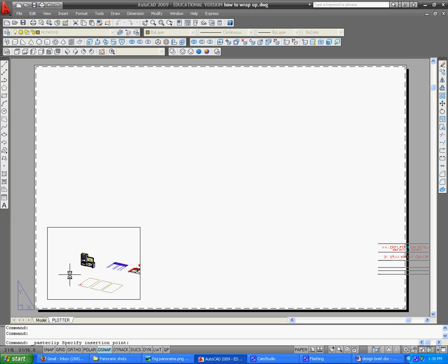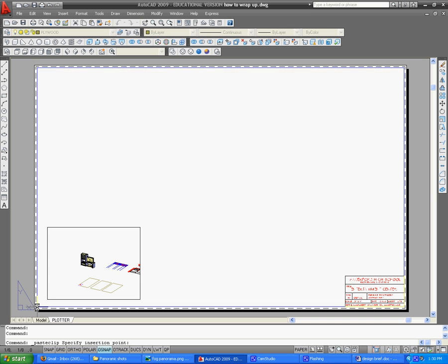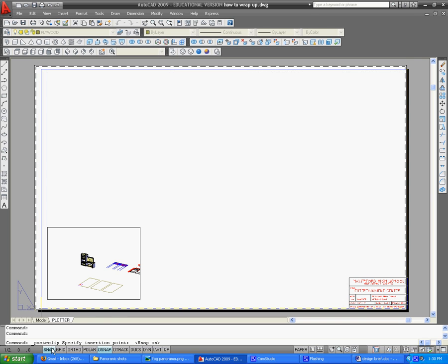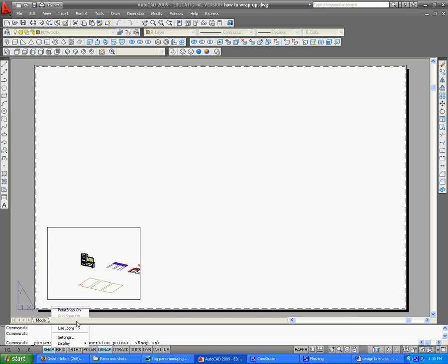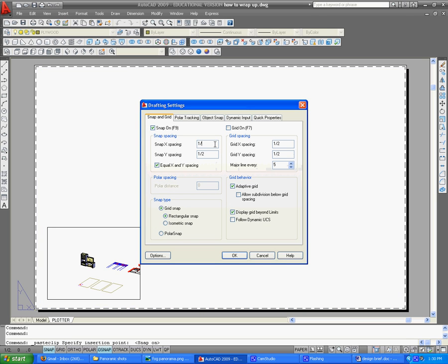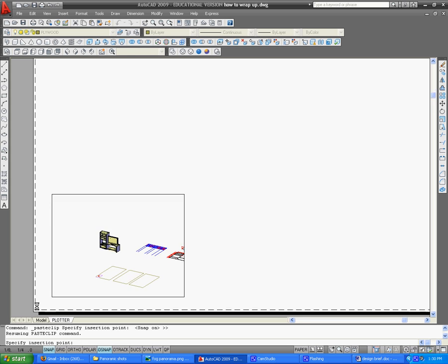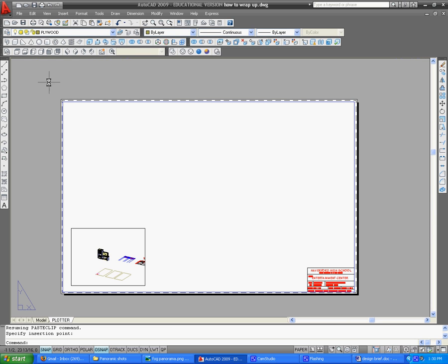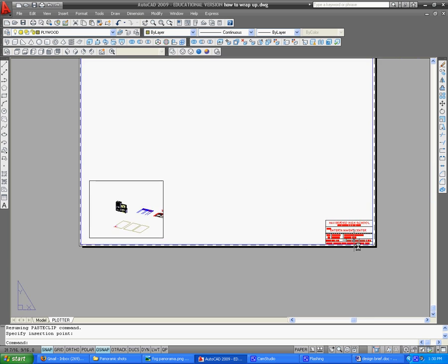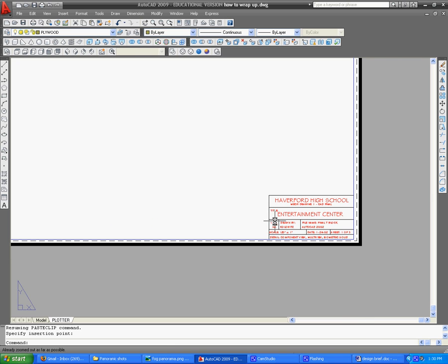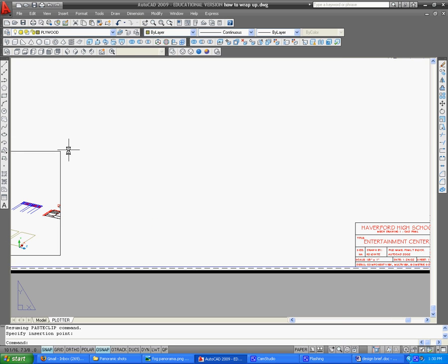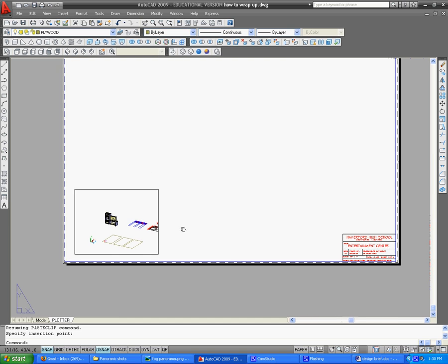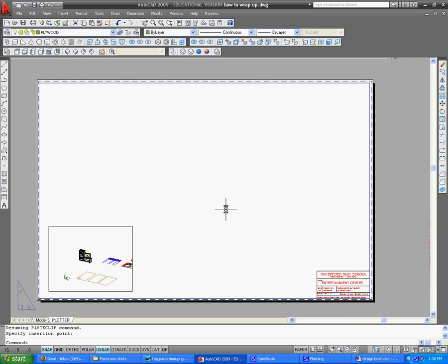And you can paste this down. It'll probably be best if you go ahead and put snap at a 16th from the beginning in paper space, and don't put it down on top of the dashed line. Now you're going to look to see it's all inside the dash, and all you have to do is edit what you need here. Now we need a bunch of 5 or 6 viewports, and we'll almost be ready to do some final formatting for the look.